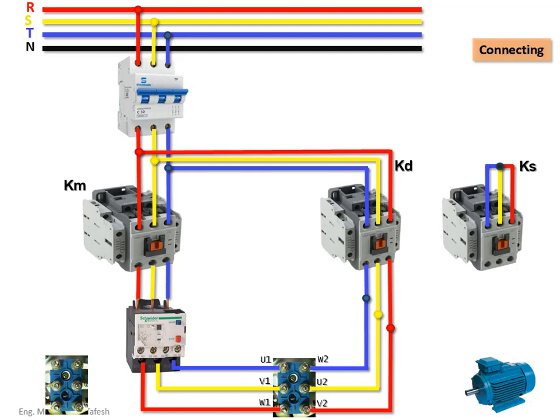it will look like this. The electricity input passes from the network through the main circuit breaker and contactor, then to the overload, then to the 3 motor input terminals U1, V1 and W1. And the 3 output terminals are connected to the phases in delta connection. This is how I have the power circuit connected correctly now.